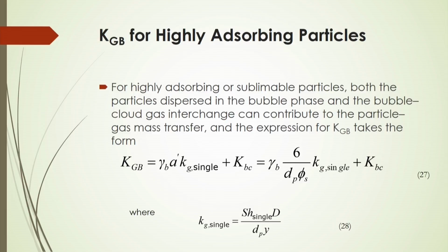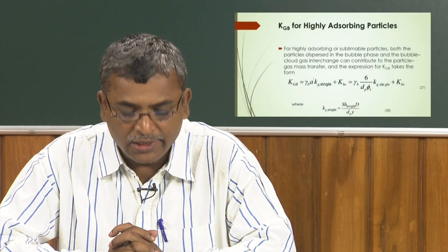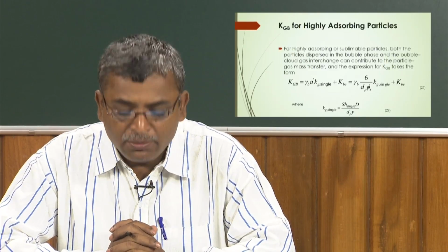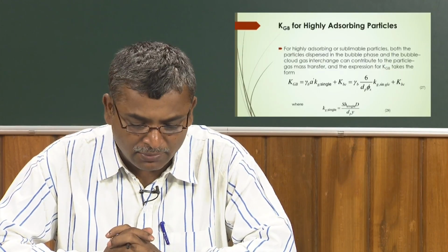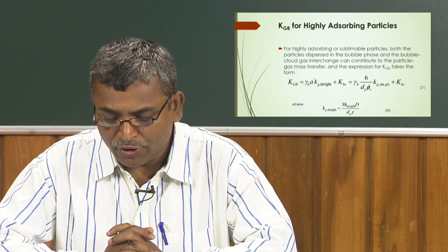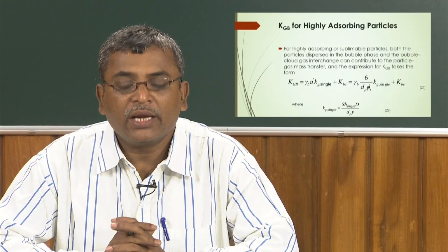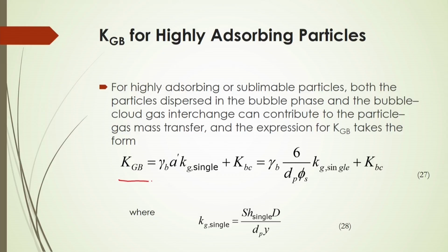Now, if there are highly adsorbing particles inside the bed, then what should be the mass transfer coefficient? For a highly adsorbing bed, or you can say sublimable particles, both the particles dispersed in the bubble phase and the bubble-cloud gas interphase can contribute to the particle-gas mass transfer, and the expression for Kgb takes the form of this equation: Kgb is equal to gamma b into A dash into Kg into single plus Kbc.